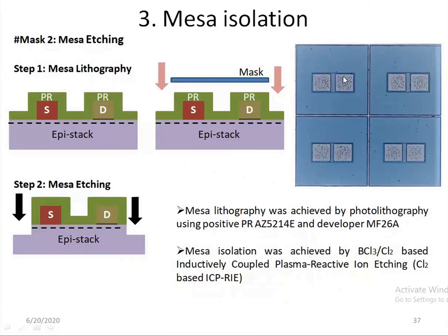When we consider the leakage currents, the channel is actually formed between the source and the drain region. Current has to flow from source to the drain. But some current can flow from the source or drain of one device to the source of the other device. So this has to be eliminated. For this, we have to remove all the paths that exist between these two areas.